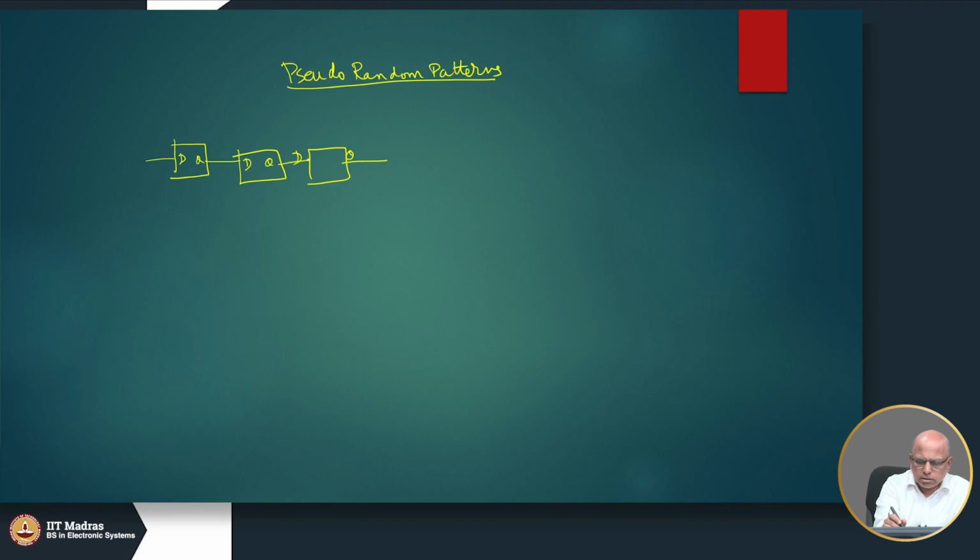This is a shift register. Now, if you are willing to take some of these outputs and feed them back, we took an XOR gate and we fed the last 2 bits and we are feeding it back.